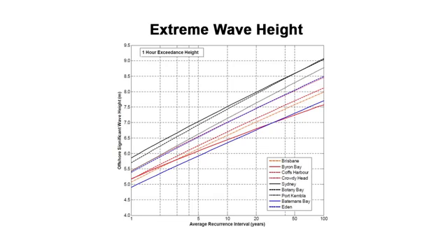and what we expect the significant wave height to be for a range. Now, the closest one to here is Brisbane, which is called Brisbane, but it's outside Stradbroke Island, off Point Lookout. The 100-year offshore wave height for Brisbane, the orange line, is around 8 metres. So that's the significant wave height. The maximum waves in a given storm can be up to twice that. So that's the sort of offshore conditions you need to design for anywhere up and down the east coast, south of, say, Fraser Island.